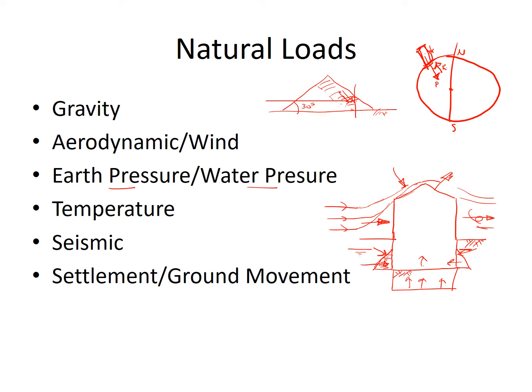And that design load is set out in the codes of practice as a return period event. So it might be the 150-year gale event or hurricane event. And again, different buildings are designed for different return periods. Different statistical models are applied depending on what code of practice you're designing to. And we will come on to look at one particular code of practice, the Eurocodes for structural design.